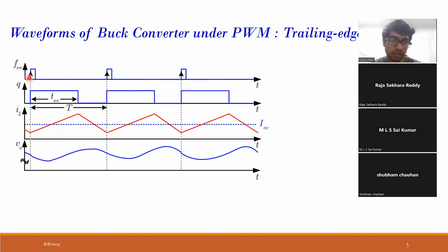Then this is a trigger signal to turn on the gate driver, turn on the PWM signal, and the inductor current rises. Then it falls. And this is the waveform of the output voltage. So in this graph, these are all analog signals. There is no signal which is digital. All the signals which we have are analog. And there is a sort of average value of the inductor current, shown by this straight line.